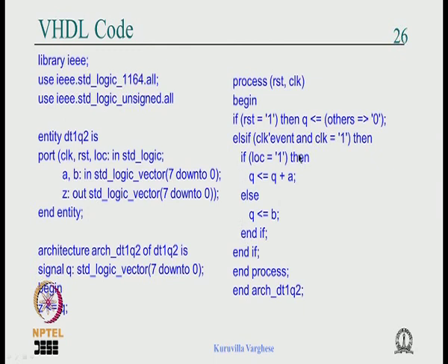So this is the 2 to 1 mux, and this plus represents the adder which comes before the 2 to 1 mux, and everything being under the clock event, clock is equal to 1, it goes to a register, to the D of the registers, all the bits, the Q7 goes to the D7 and so on.